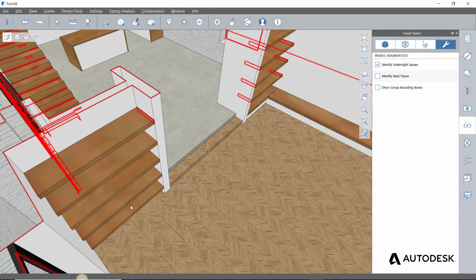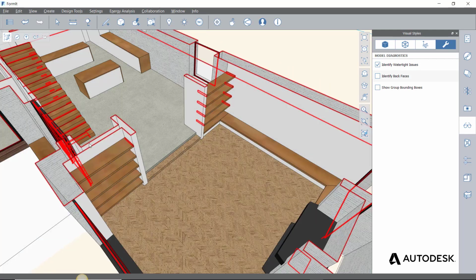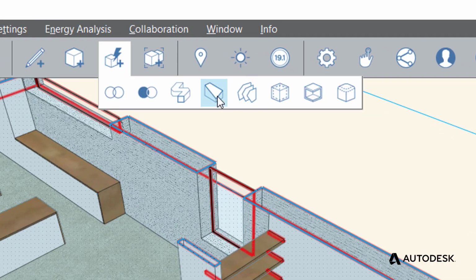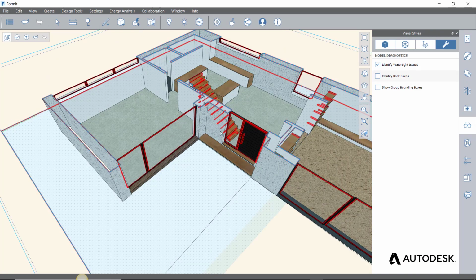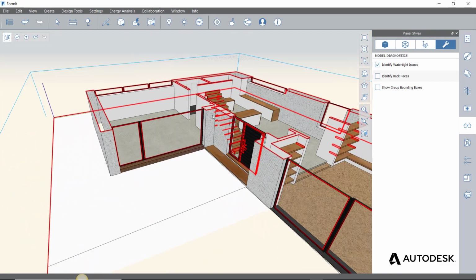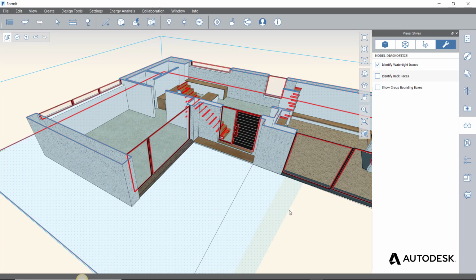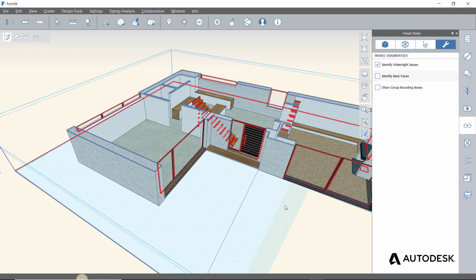Now, you could go through and start to fix these using classic 3D sketching commands. There's even a command here called cover, which allows you to select a bunch of edges and it will seal them up for you. But we're not going to go through and clean up this whole model. I just wanted to show you what you're dealing with. It's a classic case of garbage in, garbage out. You're not going to be able to work with this model unless you put a little work into it.